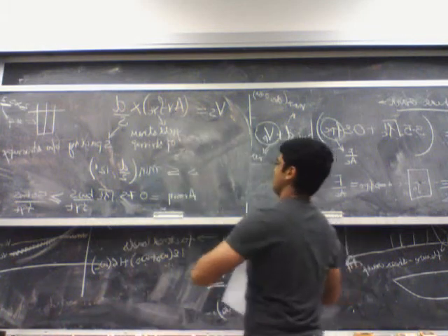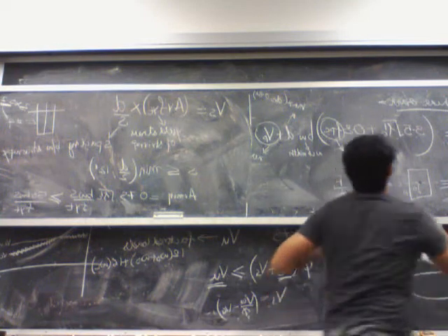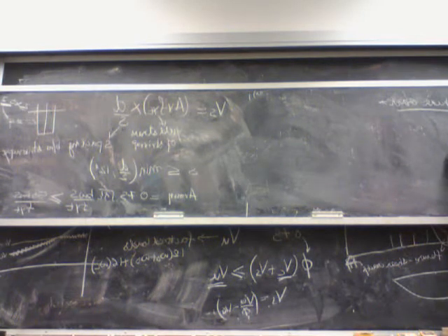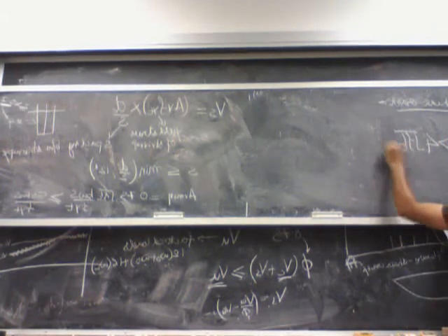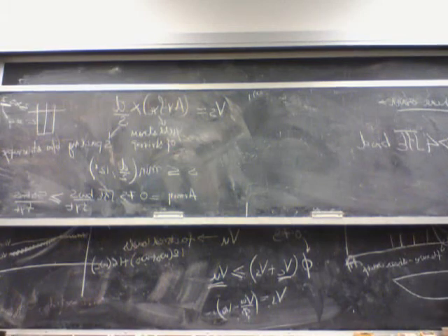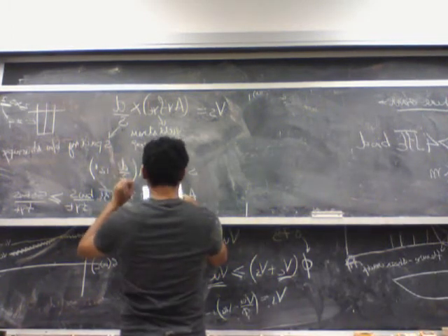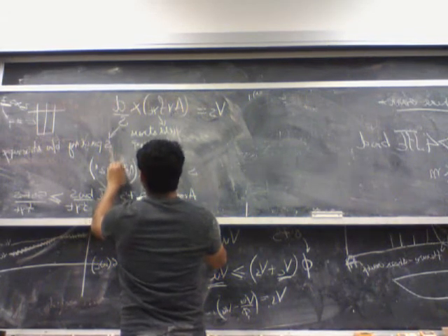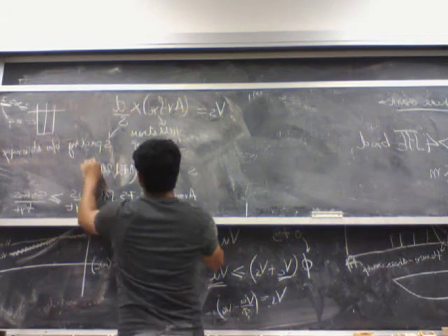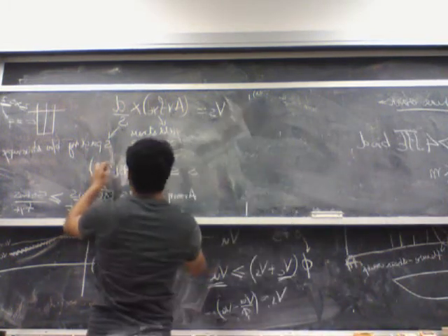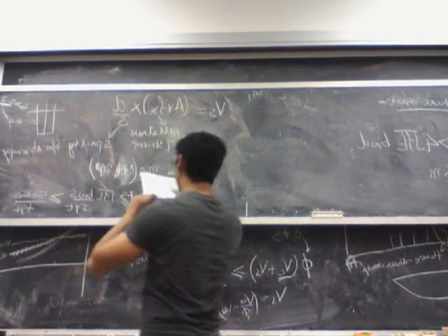And if Vs is greater than 4 square root f'c b_w d, then s has to be less than or equal to... no, hold on a second. That's for reinforced concrete. Sorry, this is 0.75 h, and this is 24 inches. Is it g or h? Oh, it's h. Thank you. So that's the total height of the cross section.